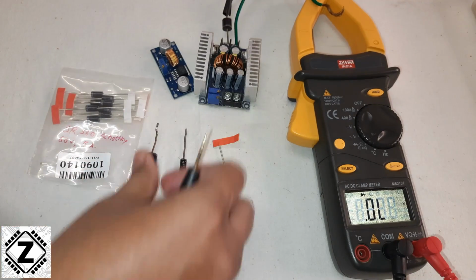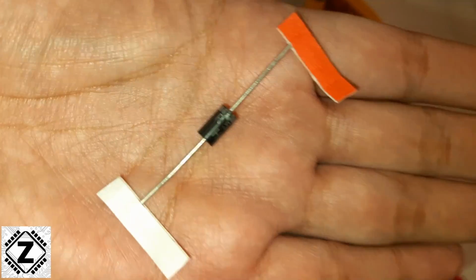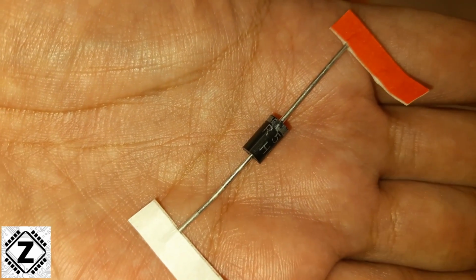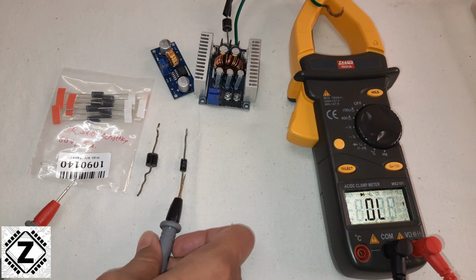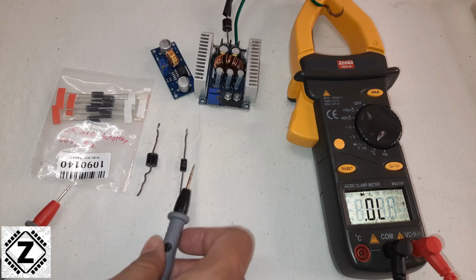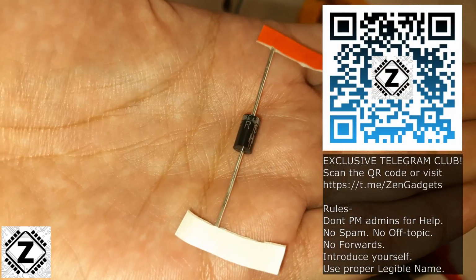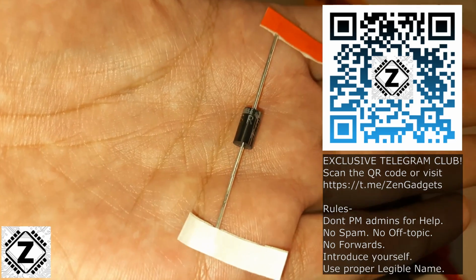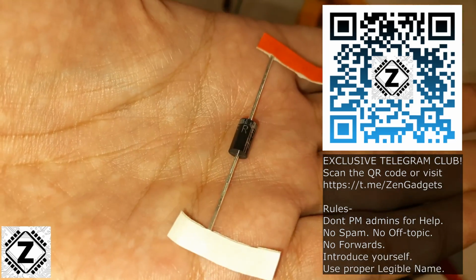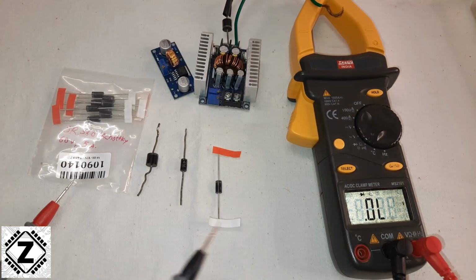But for low voltage DC applications, say if you have a power supply which provides 5 volts, and you use this diode, it's going to subtract half a volt, so the resultant output is only 4.5. That is what you don't want. So we use these, which have low dropout, and it's going to subtract only 0.2 or 0.3 volts, and hence it is better suited for low voltage DC applications.